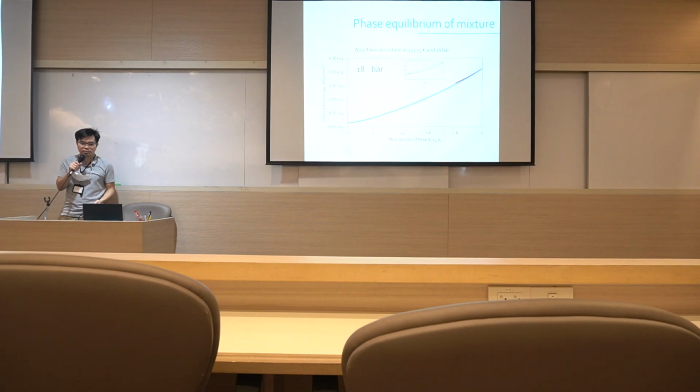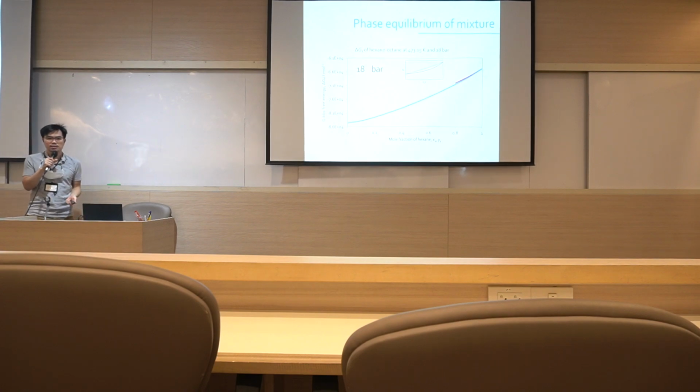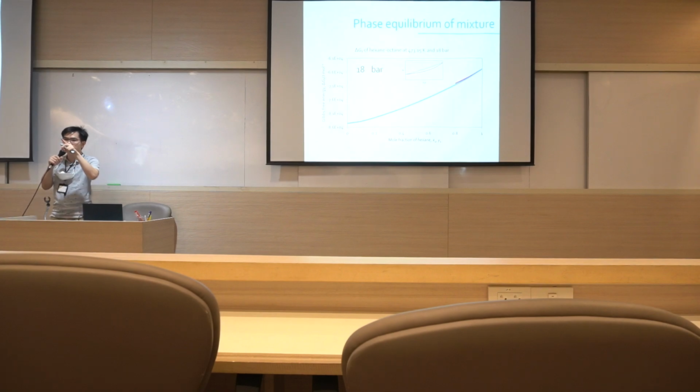Okay, and then if we increase the pressure further to 18 bar, that's similar to what we did earlier for octane. That's the vapor pressure of hexane. From the Gibbs free energy diagram, you see that the red curve and the blue curve coincide at the right hand side. So that's the vapor pressure of hexane. So that is more or less what happens thermodynamically in terms of Gibbs free energy of solutions in the two phases when we vary pressure and go through the transition from vapor to vapor-liquid equilibrium into an all-liquid phase.